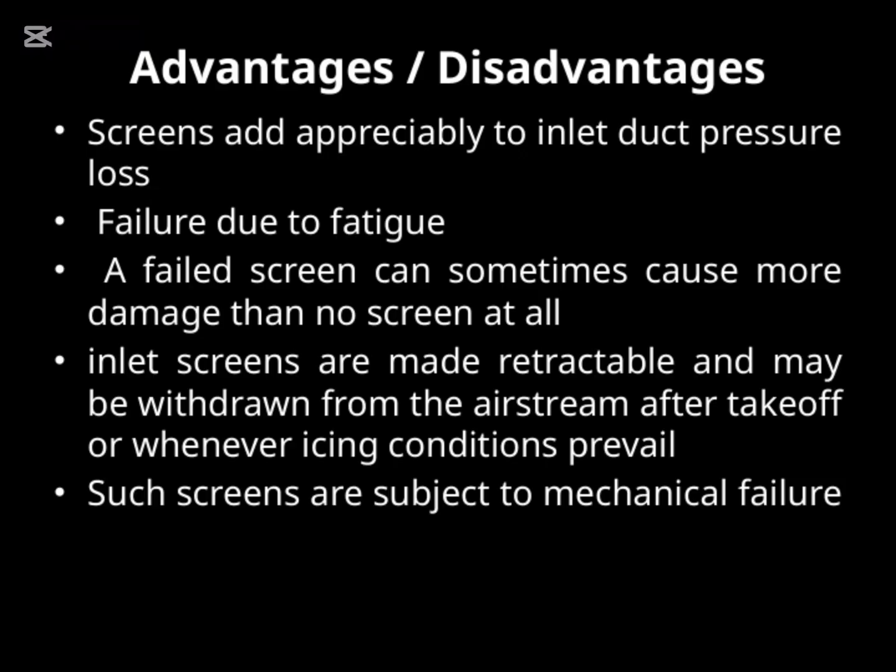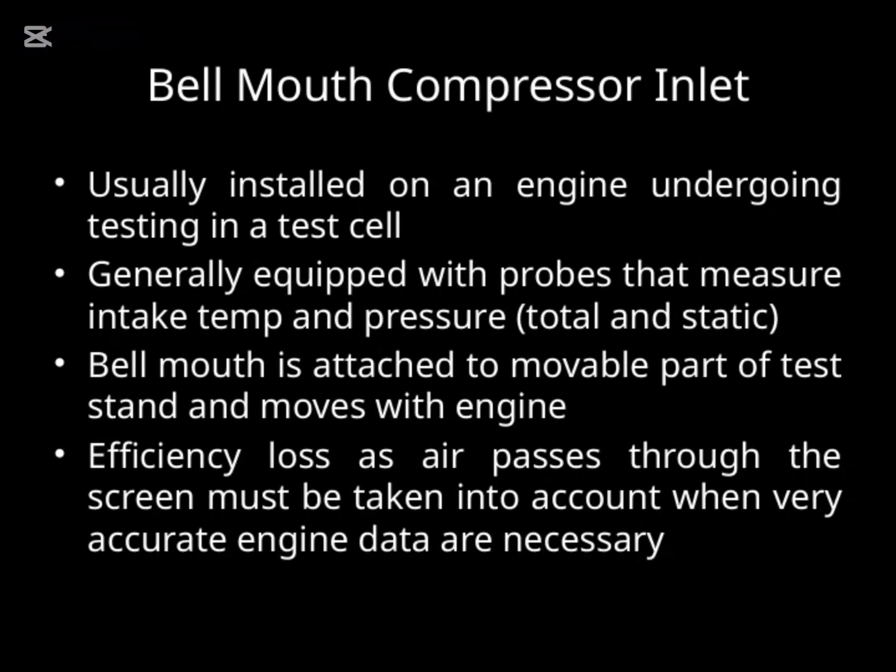That's why some aircraft are equipped with retractable inlet screens. These can be withdrawn after takeoff or whenever icing conditions are present. However, it's important to keep in mind that these retractable screens are mechanical components, and like any mechanical part, they are subject to failure. So, while they offer flexibility and protection, they also come with potential risks that need to be managed carefully. Overall, when considering inlet screens, we have to weigh their protective benefits against these operational considerations.